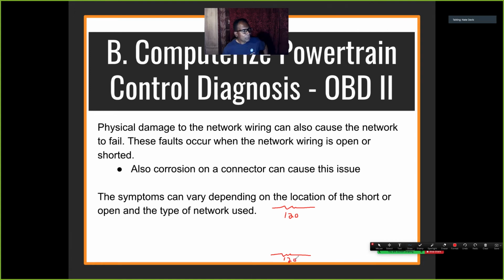On some of the diagnostic schematics, it says to place an ohmmeter across two terminals of the DLC. I forgot which two it was. And you expect to see a certain number, to see if the terminating resistors are any good, open or shorted. If they are good, what number are you supposed to see, do you think? They're actually in parallel to each other.